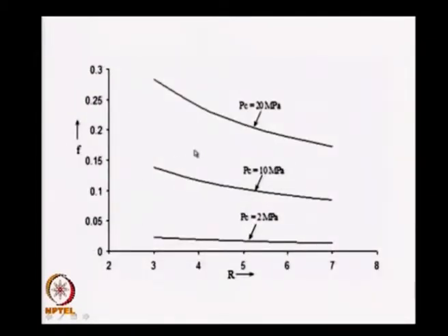Second is the same thing. If I now translate into chamber pressure, I find that the fraction of the propellant which flows through the gas generator and is not expanded adequately is large at high chamber pressure. Maybe for this particular example, I took the mixture ratio of the gas generator as something like 0.6. I took the overall mixture ratio of the engine as something like 4, eta P as 0.6, and the temperature of the gas generator as something like 900.